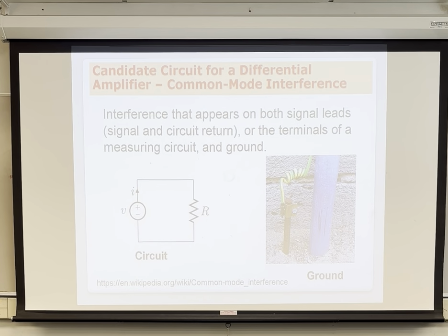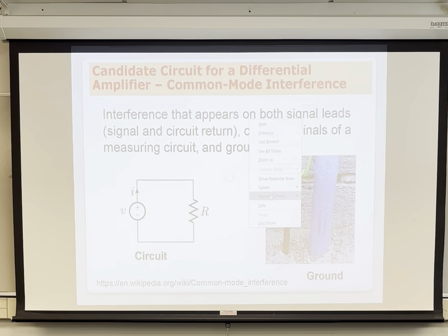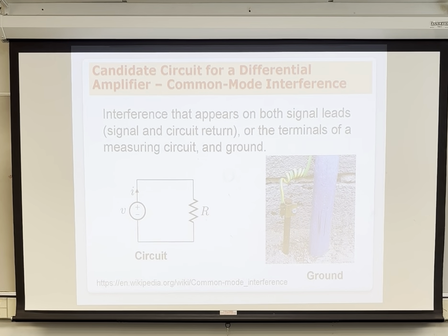This is a method that usually works with common mode signals, and that's the ground here. That's actually earth ground. So if we have a relatively good earth ground, we can short circuit signals to ground. But finding a good earth ground is not that simple to do, and this only works for low frequency signals.